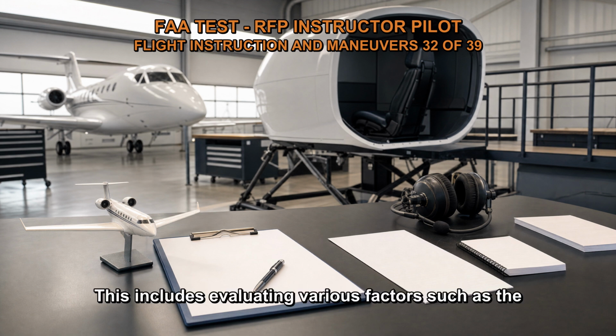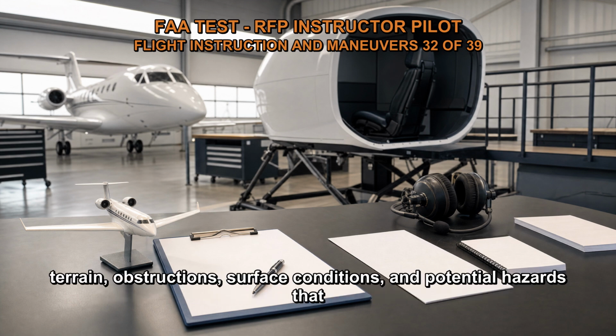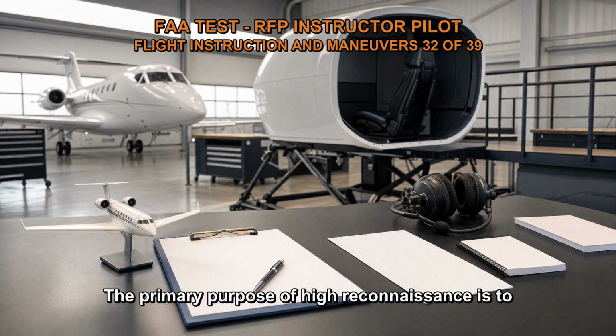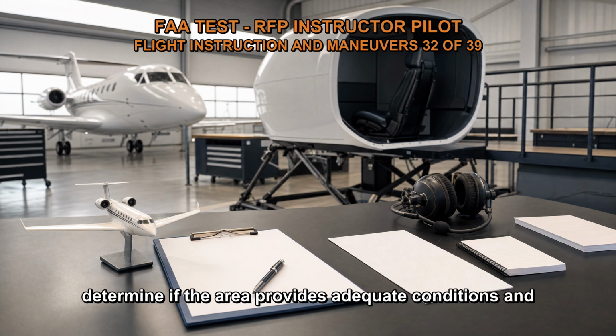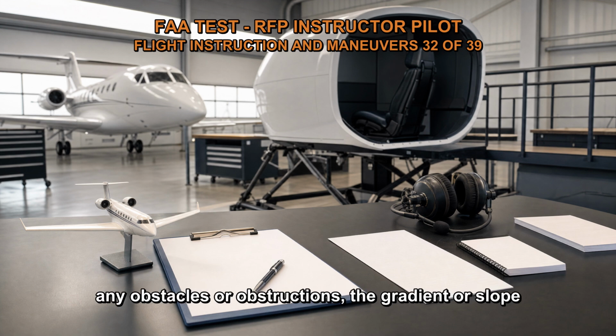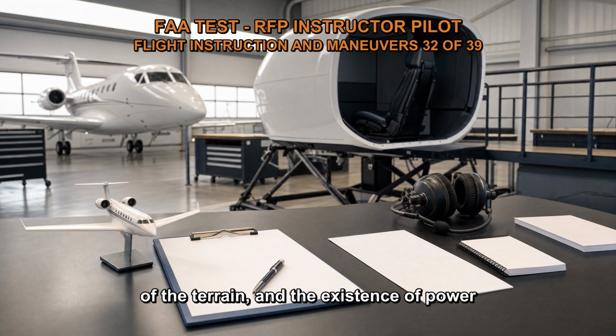suitability for landing. This includes evaluating various factors such as the terrain, obstructions, surface conditions, and potential hazards that may affect the landing. The primary purpose of high reconnaissance is to determine if the area provides adequate conditions and space for a safe landing. The pilot needs to consider the size and shape of the landing area, the presence of any obstacles or obstructions, the gradient or slope of the terrain, and the existence of power lines or other hazards.